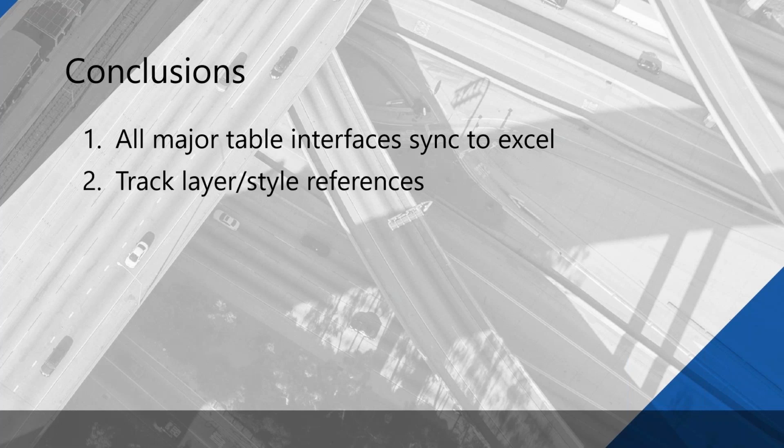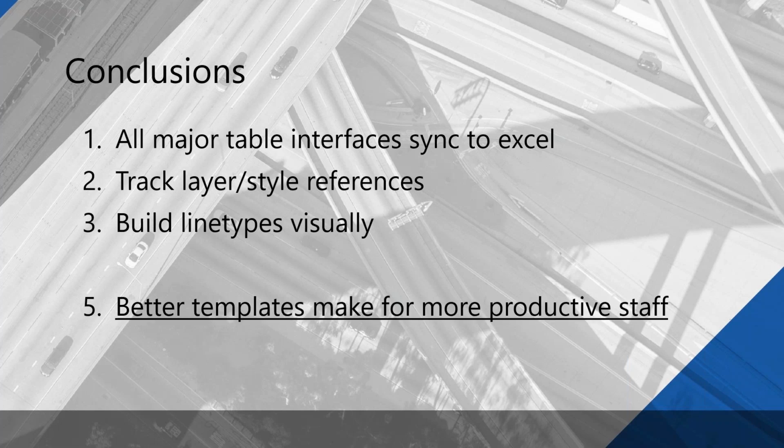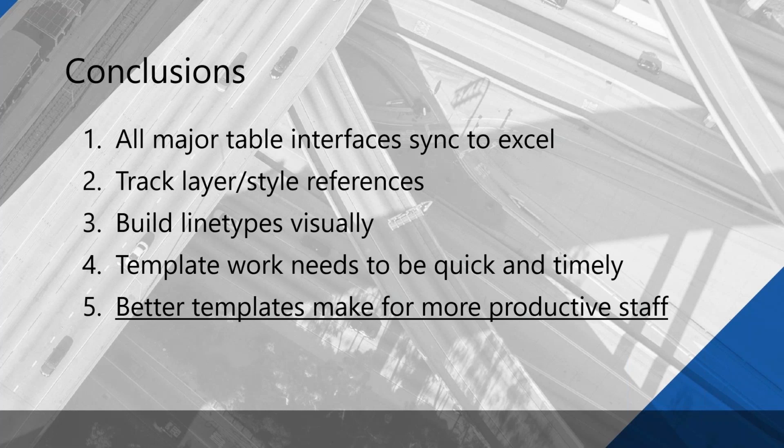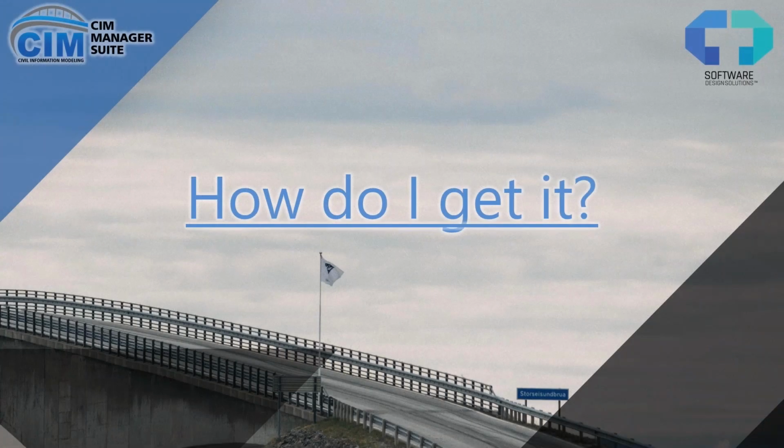We can track layer and style references, another one of the most popular tools in the suite, because you spend so much time trying to find those text style references embedded across your templates. Line type editing, right? We should have been able to do that visual line type editing 20 years ago. Anyway, it's here now. You can do it with the Linetype Manager. Template work, it really needs to be quick and timely, right? This is an important part of your guys' job. And an hour of work that you spend on your templates can save dozens of hours of work across your teams. And really, better templates make for more productive staff.